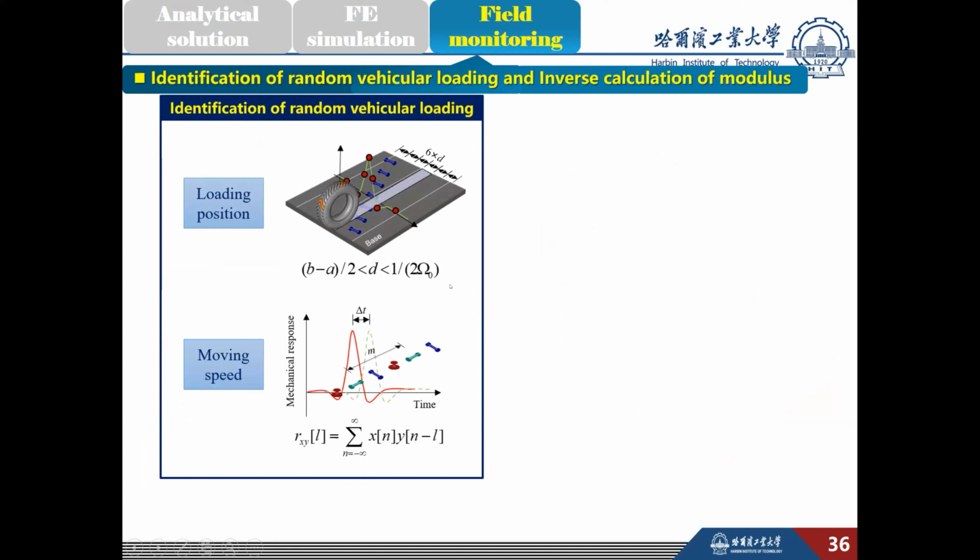So in this part, we developed 2 methods. One is that the aircraft transverse wandering has a notable effect on dynamic response. Sensors closer to the aircraft loading present higher amplitudes than others. The position identifying unit is employed to acquire the aircraft transverse offset by comparing the response peaks induced by the nose gear of the aircraft among 7 transverse string sensors.